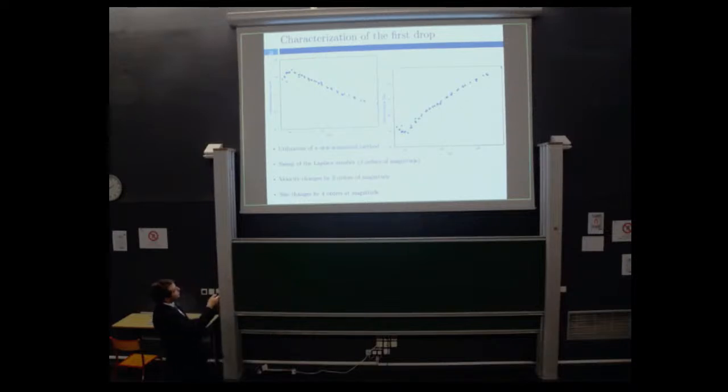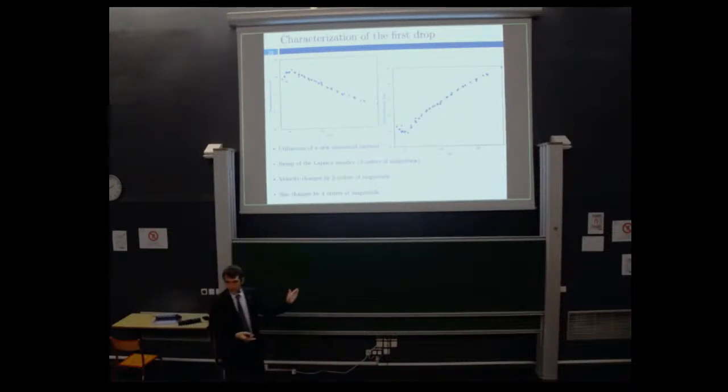And we are exploring 4 orders of magnitude in the size of the first drop, which means that the Laplace number is the important parameter. I haven't taken into account the gravity here. If you do so, you will see that gravity will only act as a correction factor on the ejection velocity and a very small correction on the first drop size. That confirms that the main parameter is the Laplace number and not the Bond number.